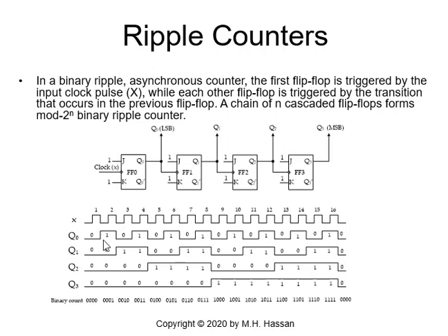However, Q0 will trigger flip-flop 1. So at the negative edge of Q0, the output of flip-flop 1 will change from 0 to 1, and so on and so forth. The same thing: at the negative edge of Q1, flip-flop 2 will be triggered and change state from 0 to 1, accordingly, and so on and so forth.